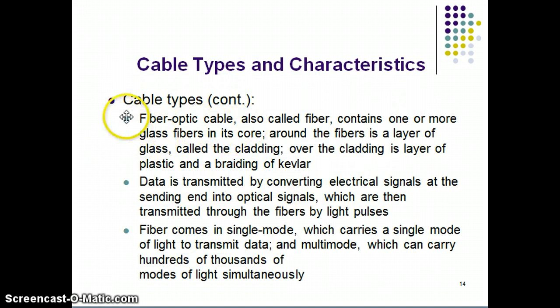Another type of cable, fiber optics. You'll get a chance to play with that a little bit. I'll teach you the safety first and then how to actually work with the cable. Now you'll be stripping it, putting connectors on, testing. Similar processes, but a different type.